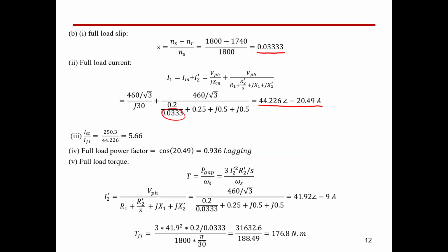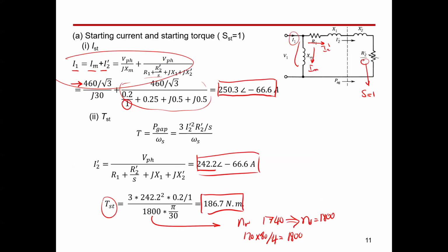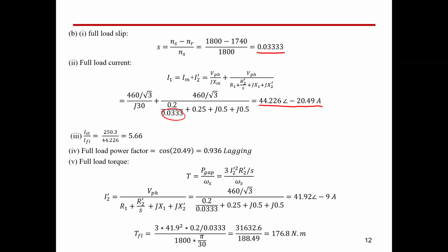Now we need to stop. Let's see, guys, how much current we have at full load compared to the current we draw at starting. Can you see, guys, 44 ampere compared to 250 ampere. So very huge value, 250 compared to 44.